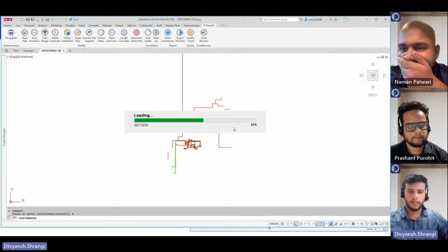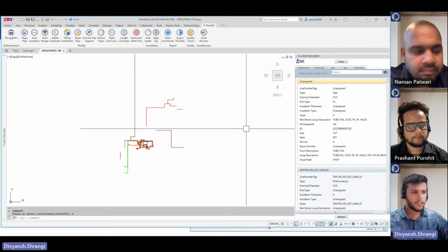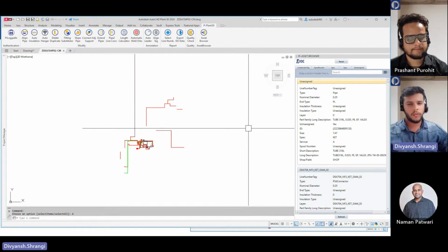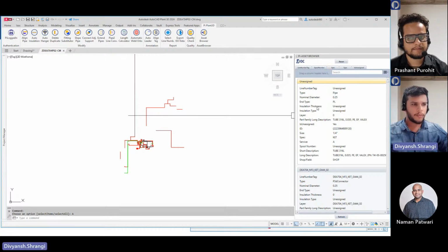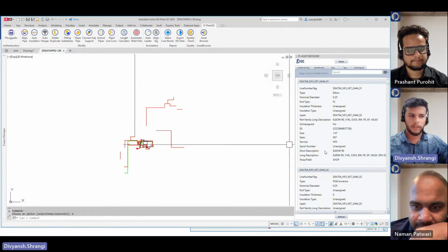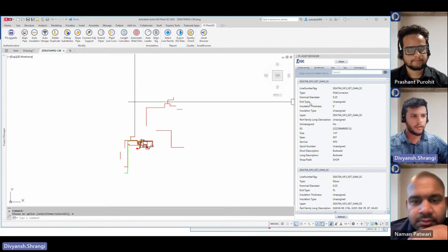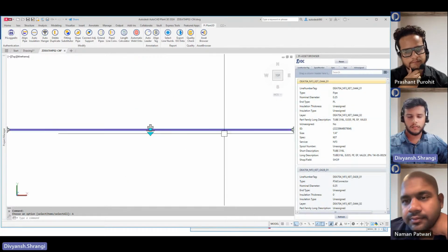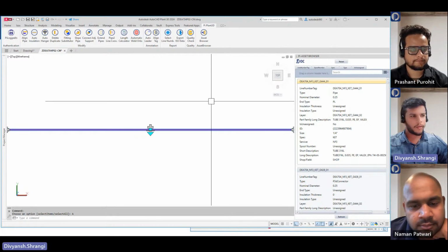While processing, as Prashant mentioned about the quick filter or quick select tool provided by AutoCAD Plant 3D, in that quick select you can only create a single level of filtration. But using this Pi Asset Browser, you can easily create multiple level filtration as well. It shows the property values of each and every item present in your current drawing file. If you want to select or review any item, you simply click on the item, and it will select it and also zoom into that particular item.